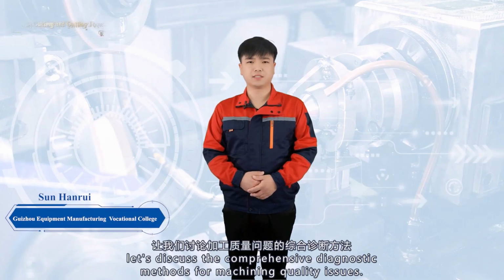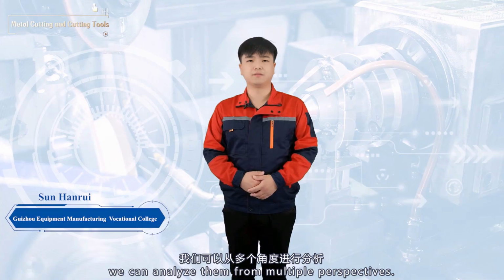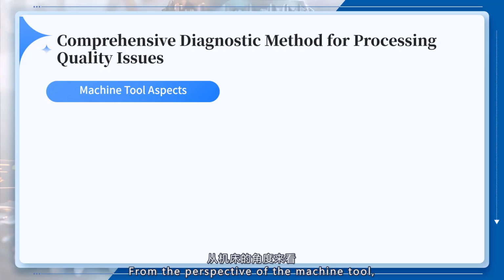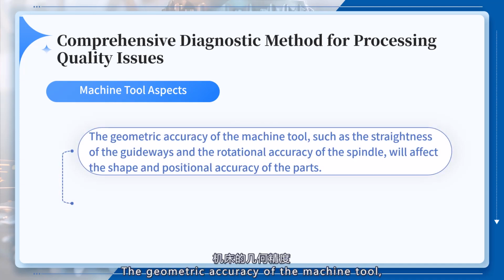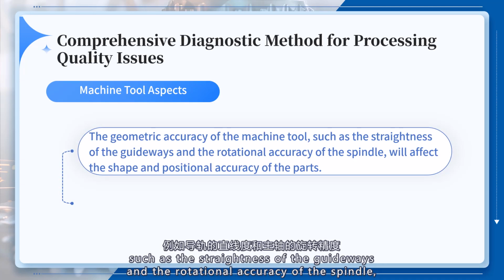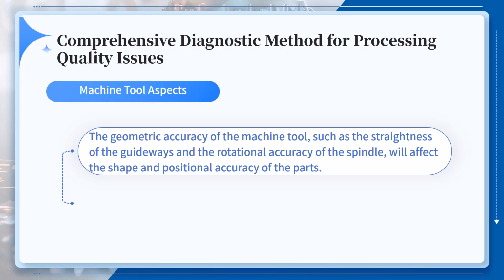Next, let's discuss the comprehensive diagnostic methods for machining quality issues. When machining quality problems arise, we can analyze them from multiple perspectives. From the perspective of the machine tool, the accuracy and performance of the machine tool directly affect machining quality. The geometric accuracy of the machine tool, such as the straightness of the guideways and the rotational accuracy of the spindle, impacts the shape and the positional accuracy of the parts.